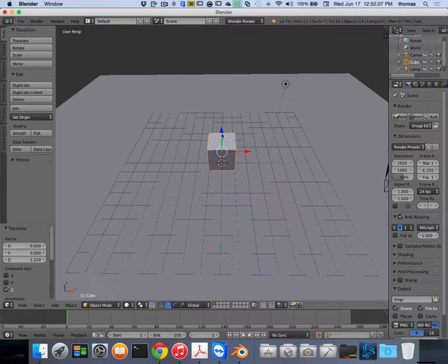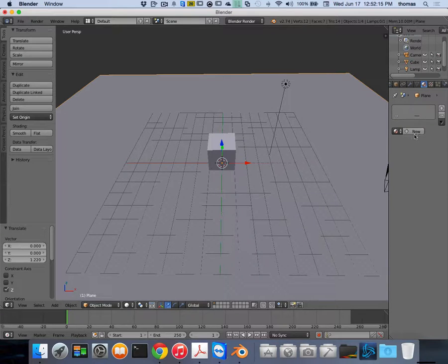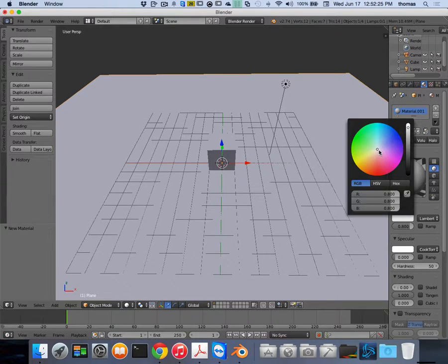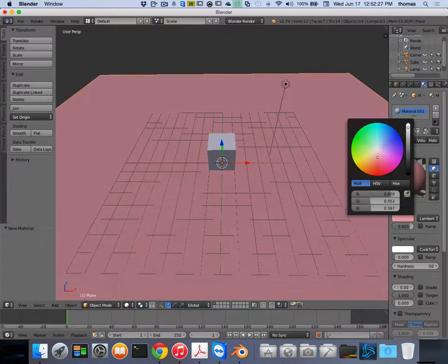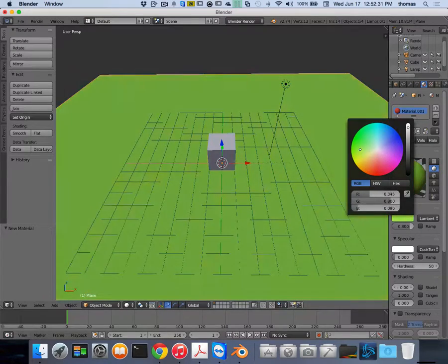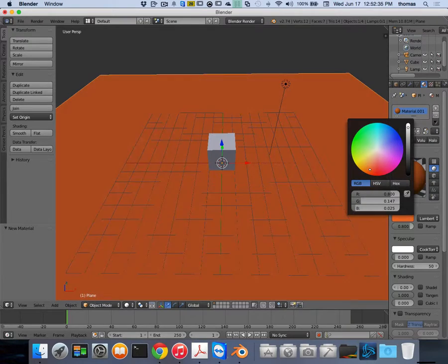Let's add some material to my object. So again, just like we did last time, here's my plane. I'm going to click that first. I'm going to go to the material button and click the material, add a new material. I'm not going to make it specular. I'm going to make it so that it's matte, right? And I'm going to go into the diffuse channel here and click on there and change my coloration, if you will, my shading to kind of a green color, or maybe more of a brown color. I think maybe brown. The browns.